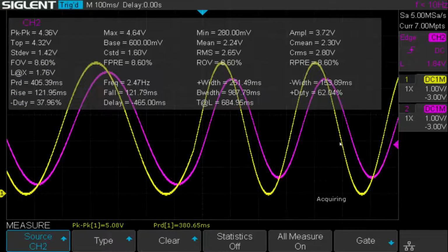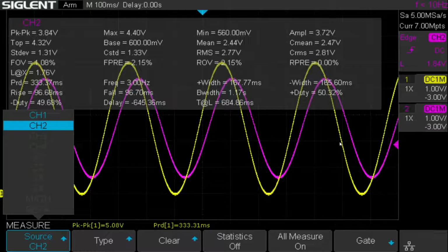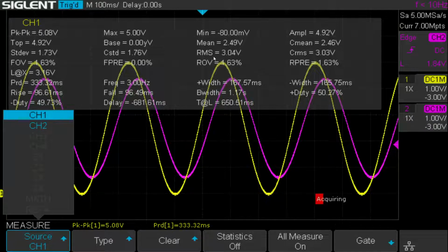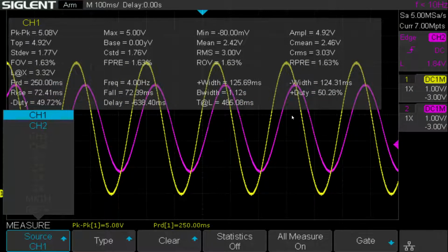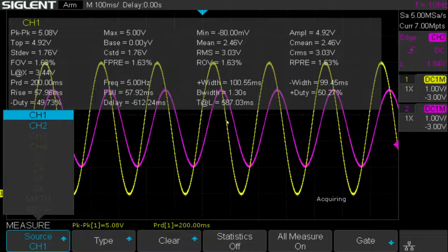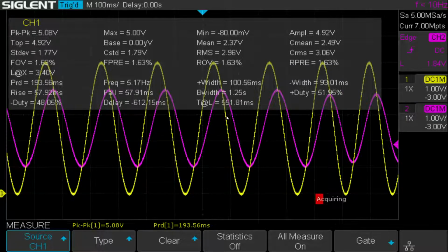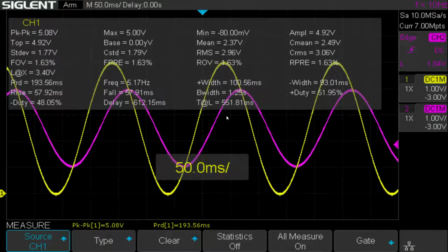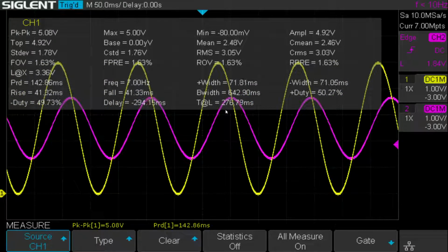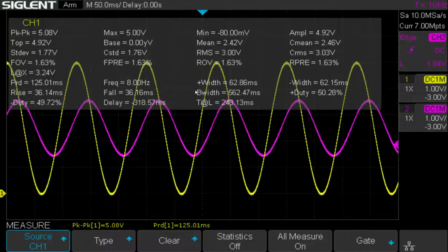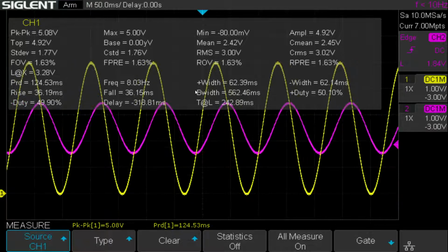I'm just going to put this as channel 1, and you can see the frequency over here is 3 hertz. And right now it's at 4 hertz. Now it's 5 hertz, and you can see it constantly becoming smaller and smaller. I'll make this a little bigger so we can see this. As I keep increasing the frequency, the magnitude is constantly decreasing. The input will always be the same with 5 hertz input, but as I keep increasing, now we're at 10 hertz.